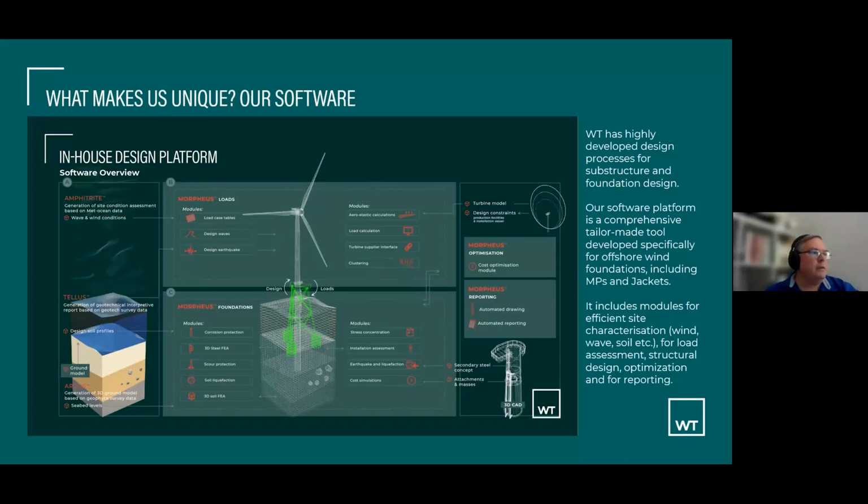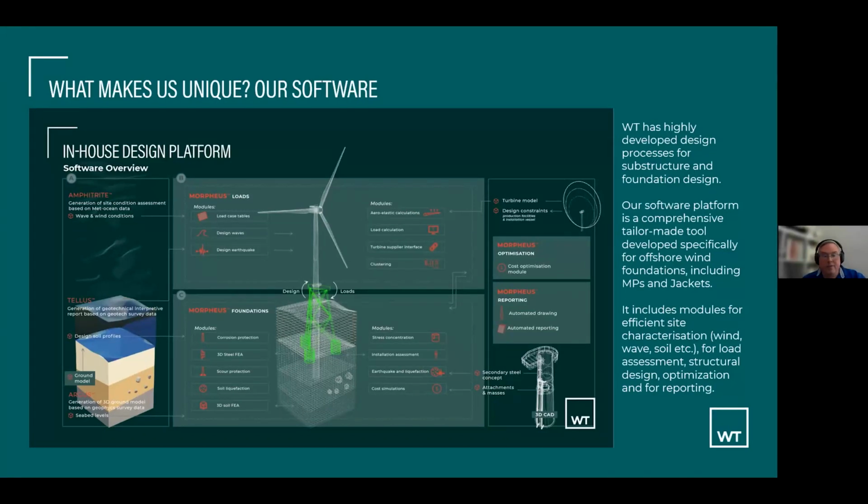And when we're doing the actual design using a specific turbine model, we're working hand in glove with the turbine OEM. They understand the aeroelastic performance of their turbine better than we possibly could because they've designed it, and each one of the manufacturers keeps all of that information as secret as they possibly can. So we have to get into an interactive load iteration process with the designer where we will initially come up with a rough foundation design, not using their loads initially. We give that to them.